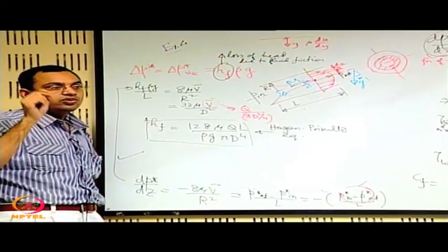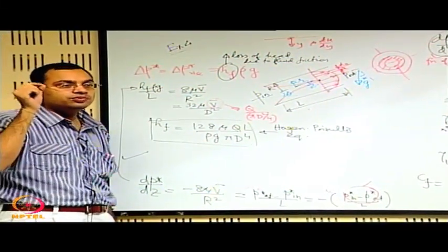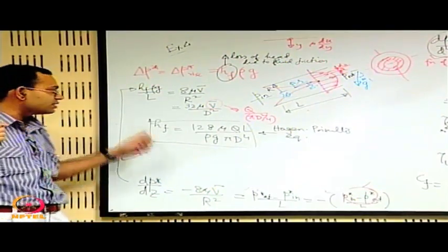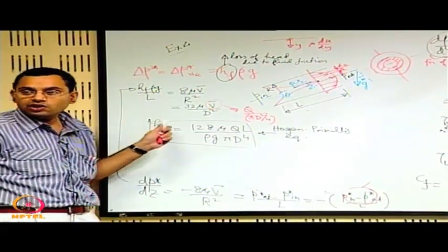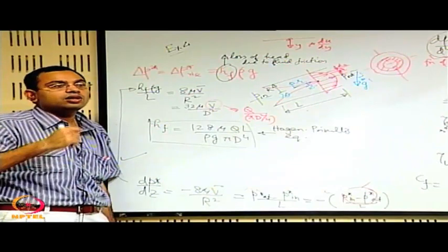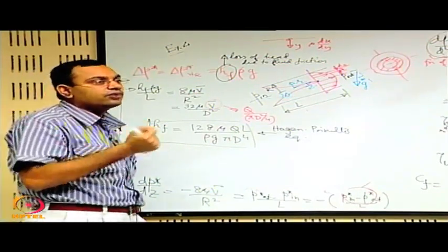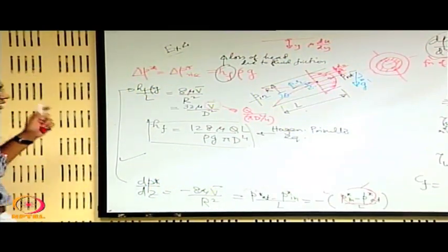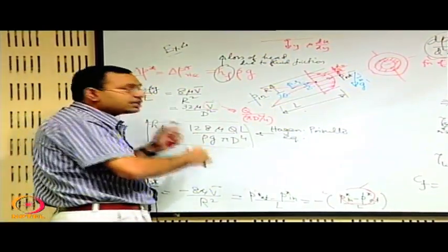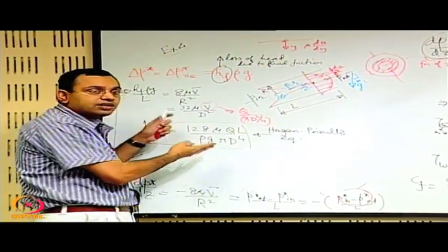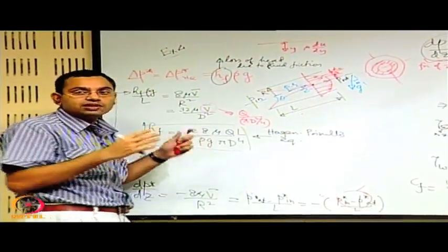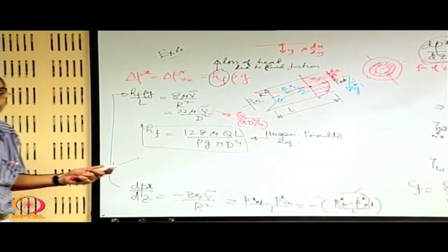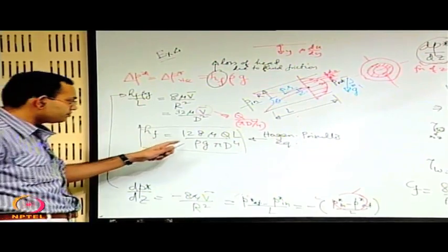That means to drive flow through a very small tube, say a tube of micron size, you require a huge pumping power, because there is a huge head loss because of the frictional effects. That is one of the challenges in having a flow in a micro or a nano channel, in a very small channel. Those are advanced topics, but you see that the basics of fluid mechanics give us a clue about the engineering challenges in having the flow as you make the sizes smaller and smaller.